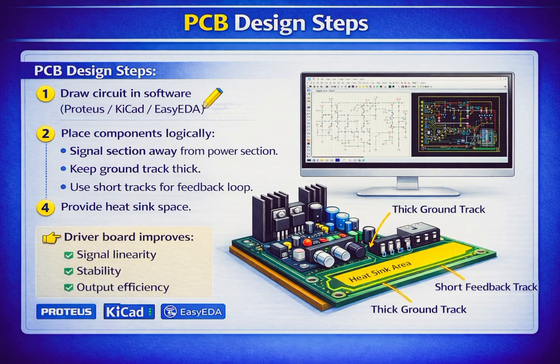Keep the signal section away from the power section to reduce noise. Second, use thick ground tracks for better current flow. Third, keep feedback paths short to maintain signal stability. Finally, provide enough space for heat sinks, especially for driver and power transistors. A good PCB layout improves amplifier performance significantly.